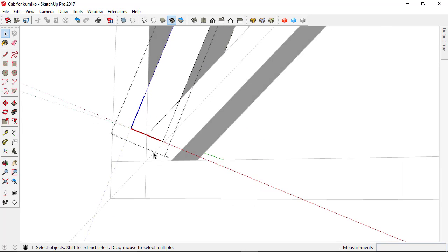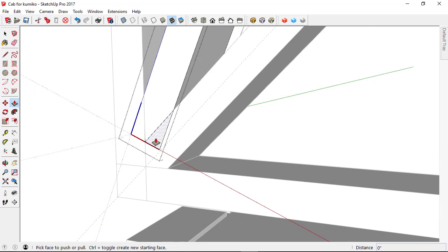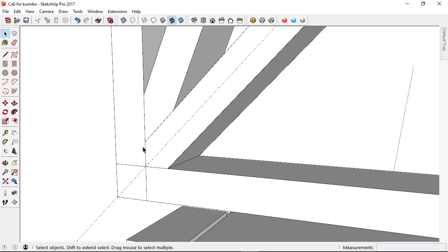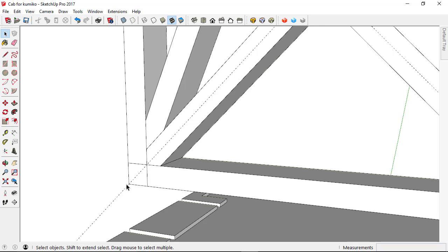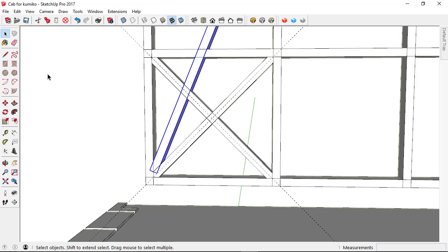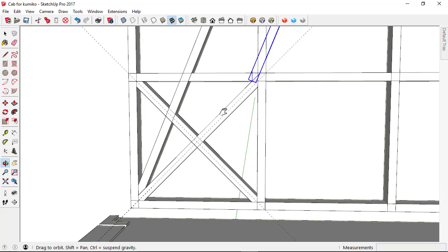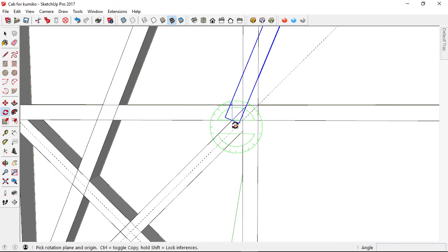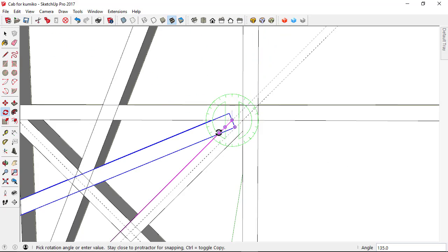And since the bottom edge was right at the corner point here, I had to click an extra time to drag out the two lines here. The first one I did, the end of it was way down here at this corner, so when I drew the miters, it worked out exactly the way it should. And one push-pull, it really amounts to the same sort of thing here. Now this one gets copied, and again, I'll just rotate that into position.